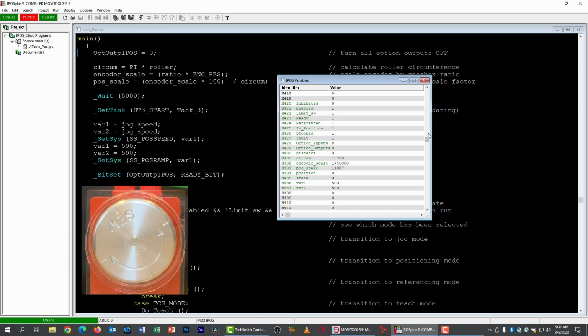That indeed stopped the drive. And of course, I have a fault as well. I'm going to turn the limit switch back on now. Now the limit switch is cleared, but the drive is still in dispatch. That's because the fault isn't clear yet. I have to clear the fault. I'll toggle DI7, and that got rid of the fault. The drive resumed operation. Let me check the other limit switch just for thoroughness. That too stopped the drive and faulted it. Let me turn it back on and reset.